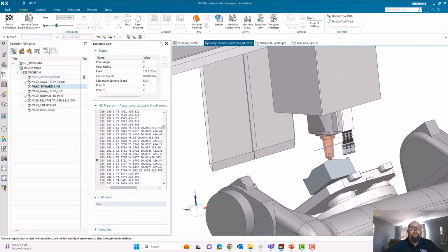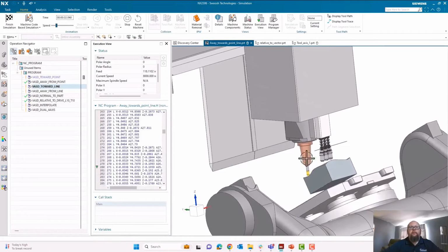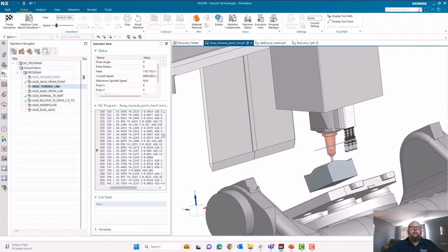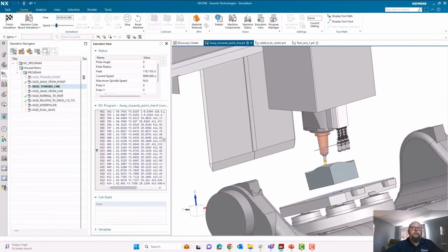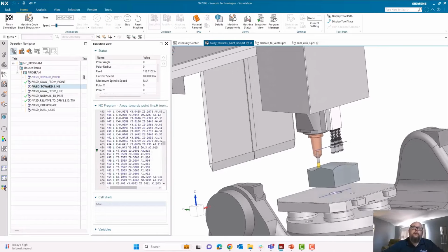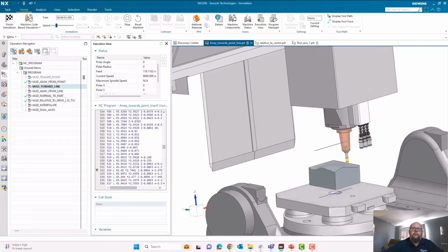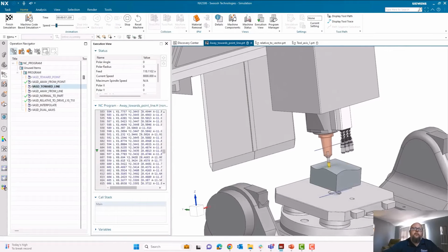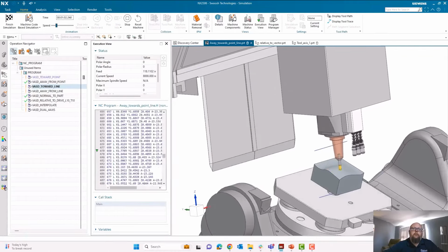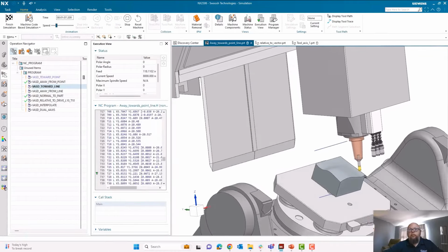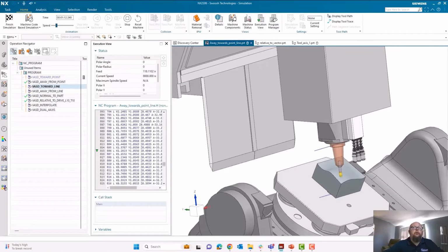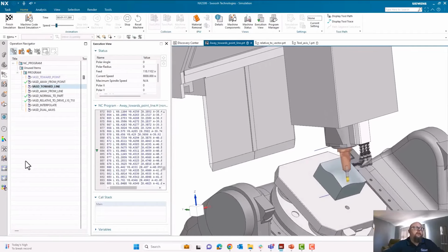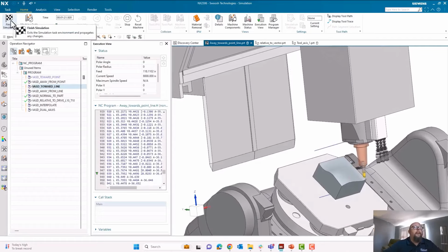And we can see that now we're not getting any C-axis motions, because my line is right along my X-axis. So we're only rotating that A-axis. That's all that's taking place on this particular part. So again, maybe a better approach. It depends on your requirements, so that's something to always keep in mind.